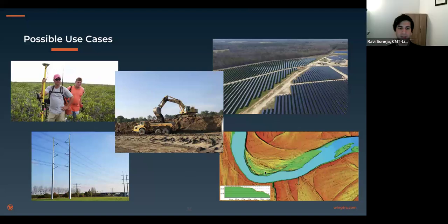I can speak to that. I'm kind of cheating with this because I've used this same laser head, just a different integration, at a previous company I worked at. So I've had some experience with it. The system works for mapping transmission wires. You have to be very careful about the AGL at which you fly. That's the primary driving factor to being able to pick up some of those smaller features, either the static wire at the top or the guy wires on the ground.